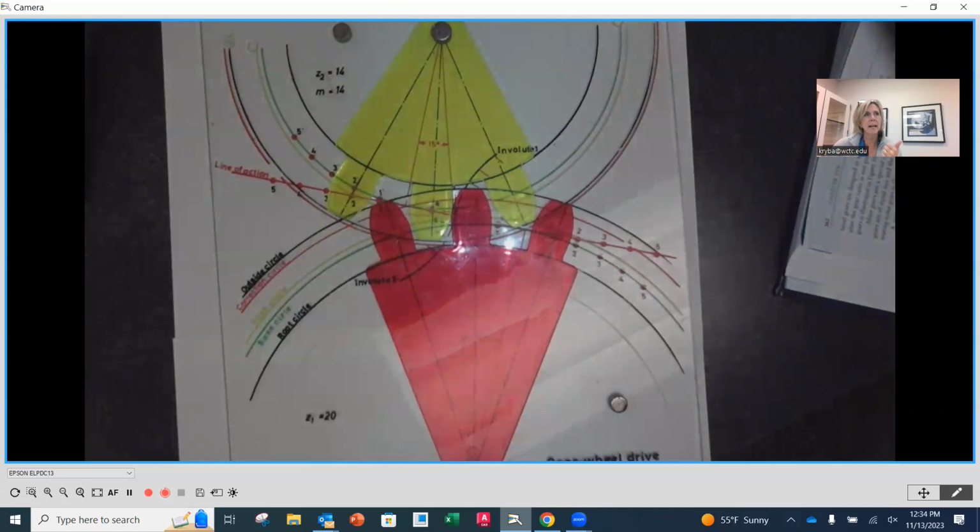Now, 14.5 is for replacement parts only. We do not make any new designs with 14.5 pressure angle, ever. 20 and 25 degree pressure angles are the most popular, with 20 being the most universal. So what do you mean by a replacement part?